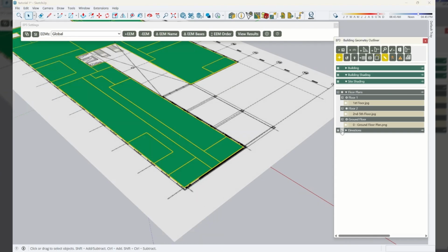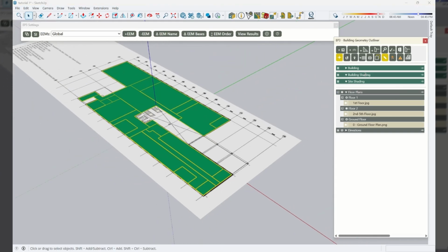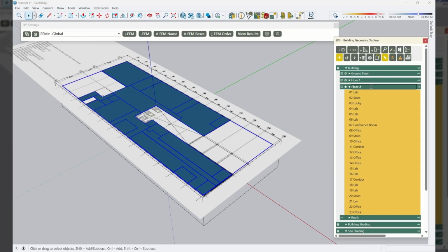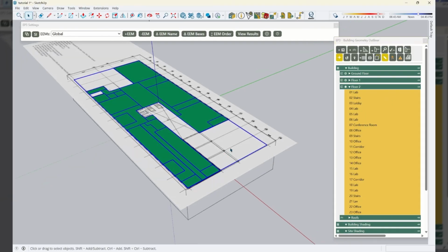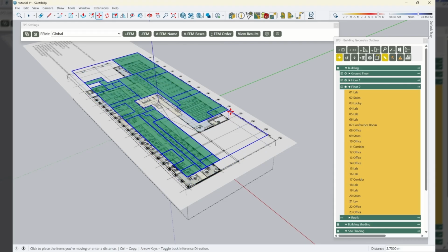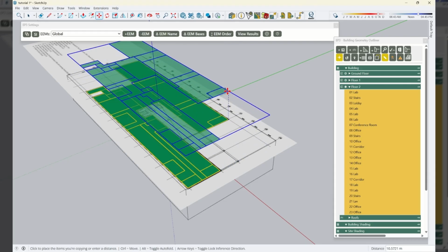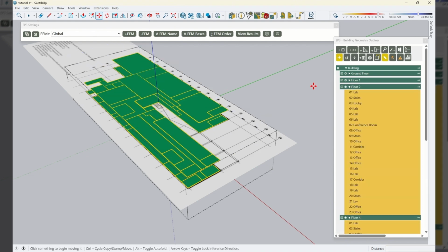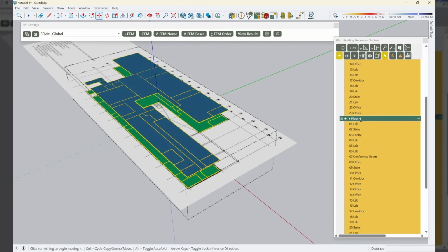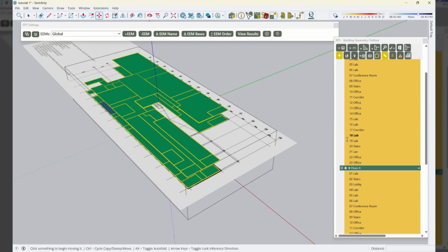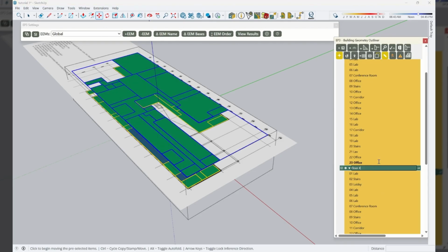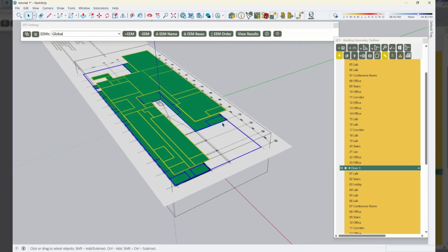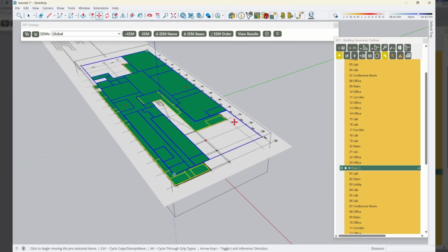Okay, so I'm going to hide the elevation, and then I will select this floor, and I'll use the move tool, M, and I'll click a corner, and I'll click Control, so it copies, and I'll hit on the keyboard 3.7 M and enter. So now it's given us floor 4. So we'll go in and rename these afterwards. Or I can do this now. Floor 3.